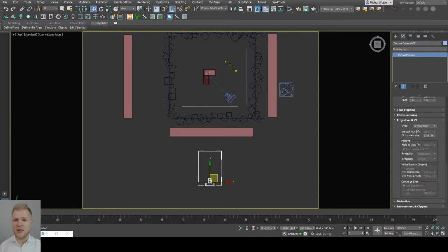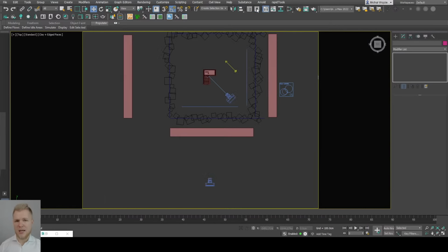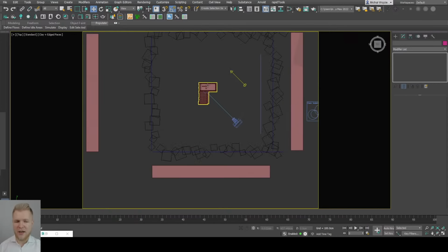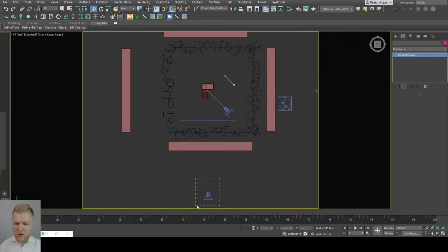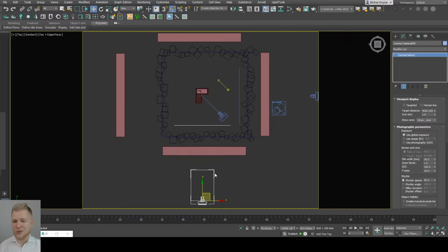Also, please check if the layer which the file is imported at is not just turned off. Sometimes that's going to be the case, and if you're working with default scenes, you may actually have this problem. We go over scene management a little bit deeper during the first week of our course. So in this case, it would probably be this solution.